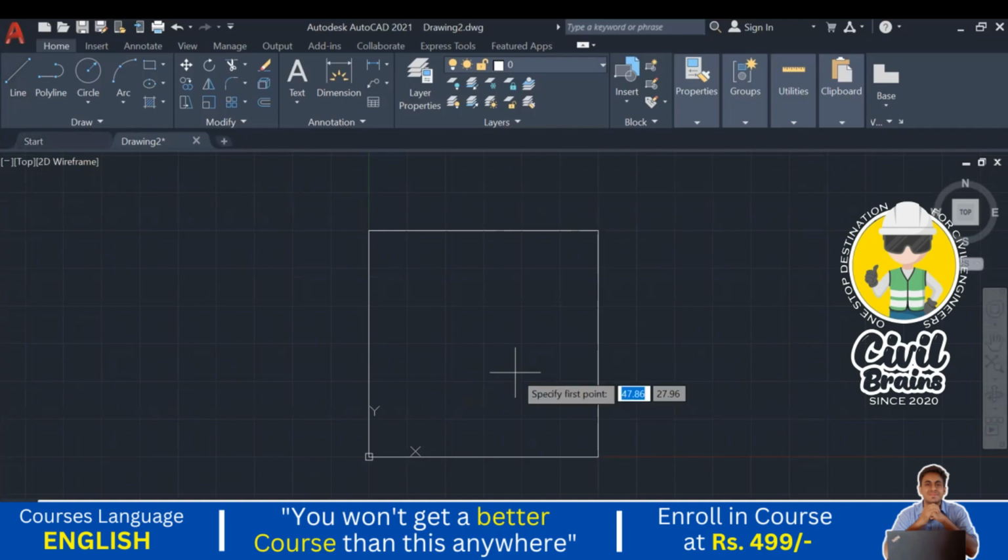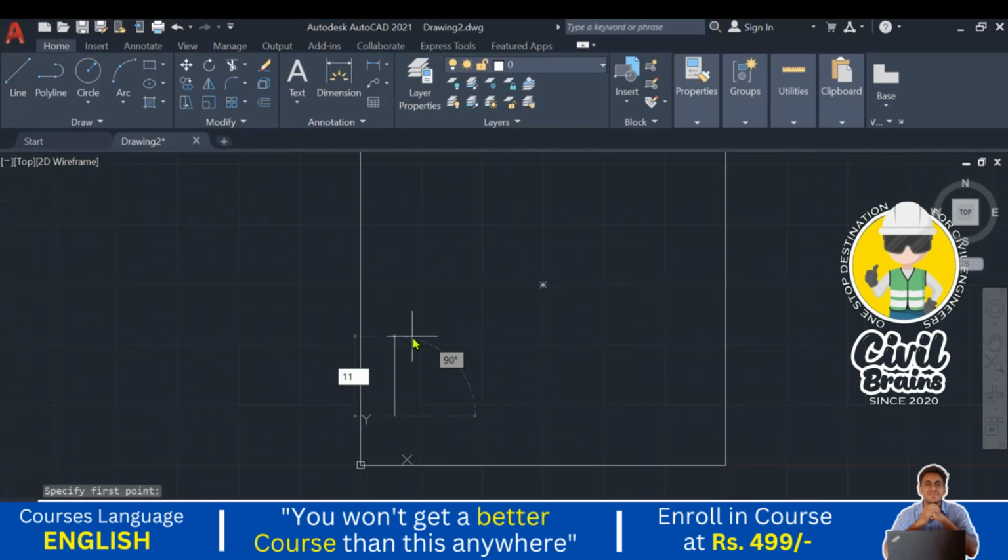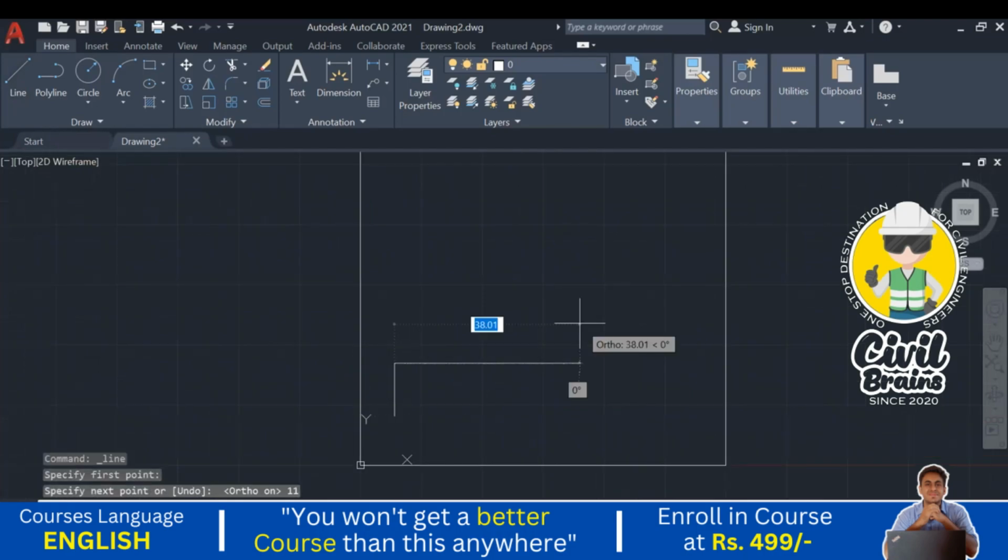I just start from here. What is the length? For the length, with ortho mode on, I just type 11 meter, plus enter. 10.5, press enter.